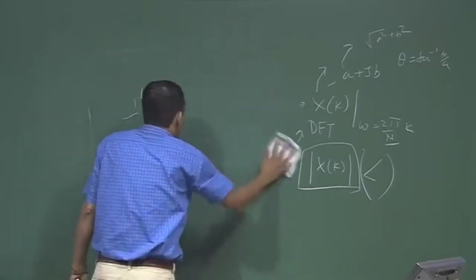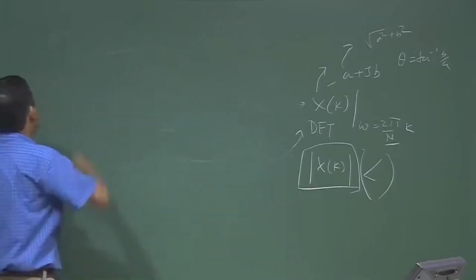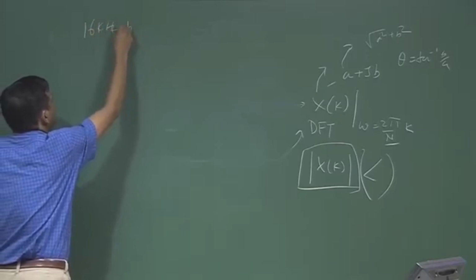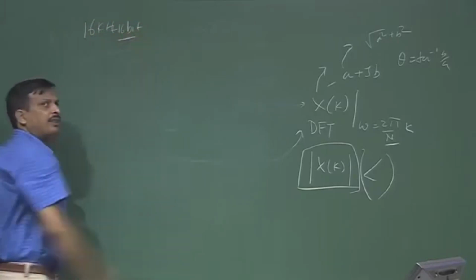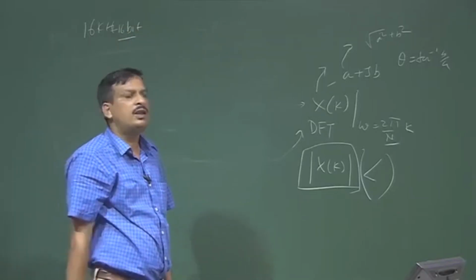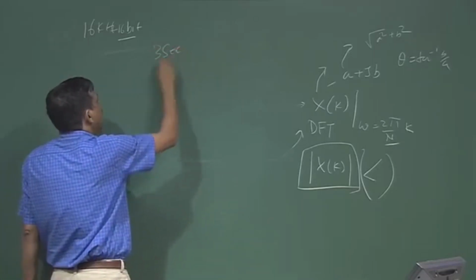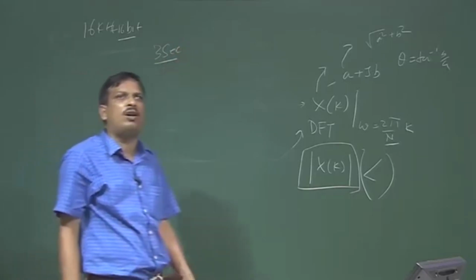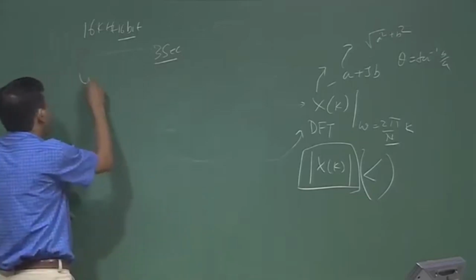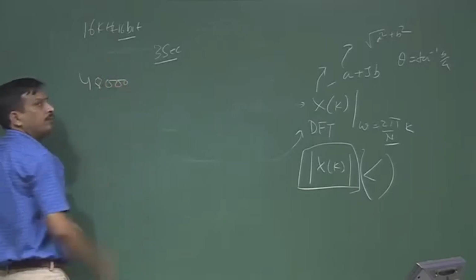Okay. So, I have recorded my voice of a sentence, and it is 1 second long, sampled at 16 kilohertz with 16 bit. So, each sample is encoded with 16 bits and the sampling frequency is 16 kilohertz. Suppose I record a sentence which is 3 seconds long. How many samples will there be? 3 into 16k, so 48,000 samples will be there.